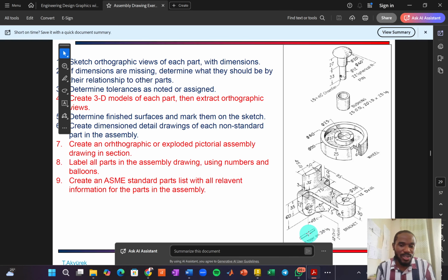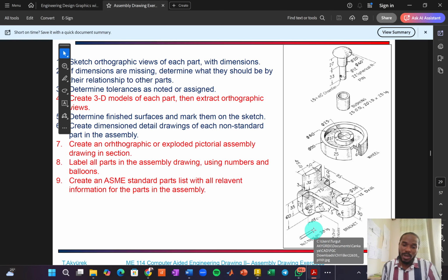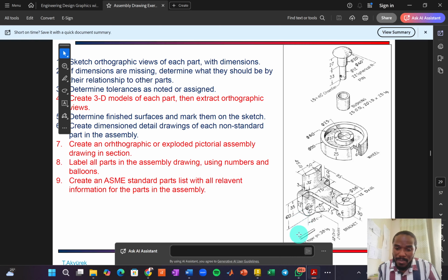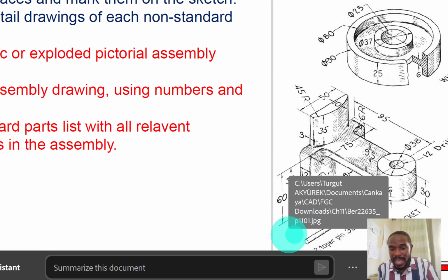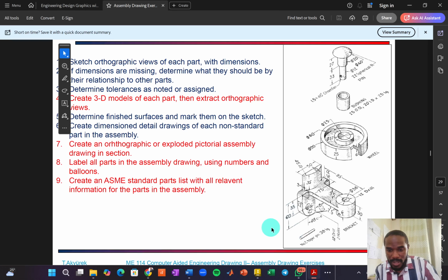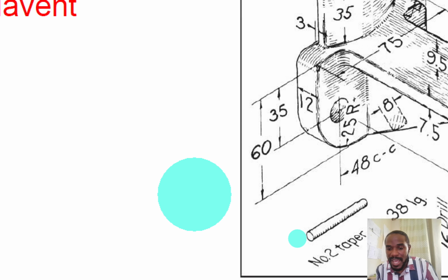We did those calculations in class. You go to websites or you find a data sheet for tapered pins. We're looking at number 2, and then they give you all the dimensions that are needed. Even though it was in inches, we converted them. The bigger end of the taper pin from the data sheet is about 4.8514 millimeters.